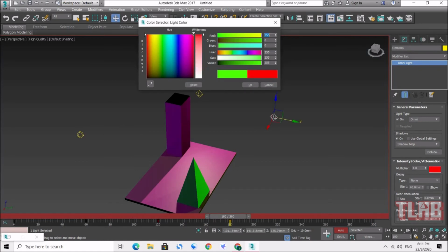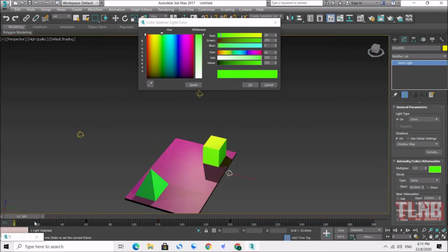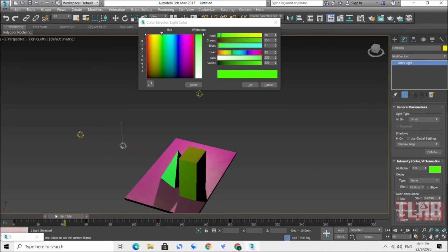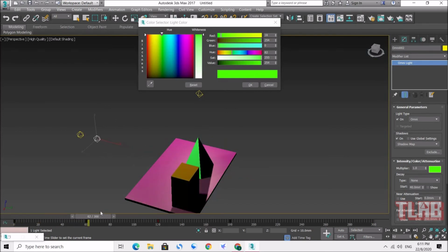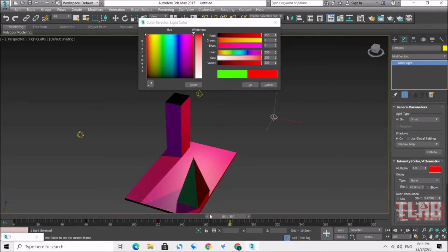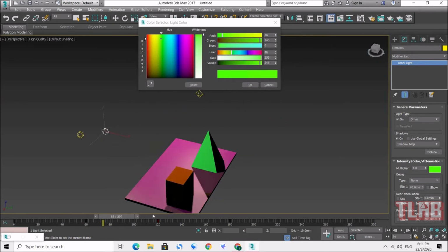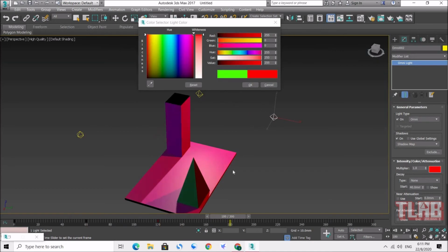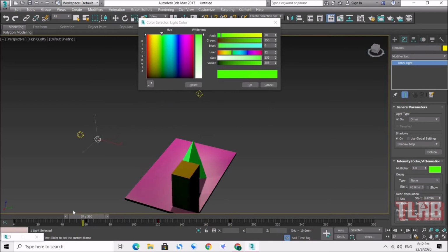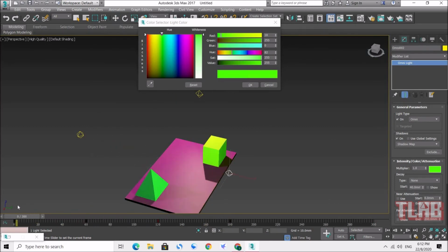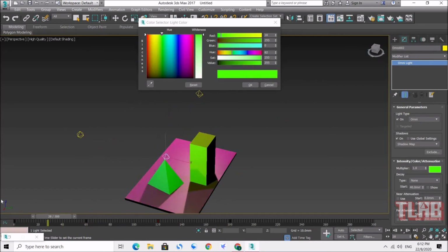You can put maybe a red color, like I said just now, 255, 0, 0. So now auto key off. Now you can see 0 until 60 is still the same color. Then from frame 60 until frame 180, you can see the number keep changing, so that means the color also keeps changing. You see this one. The 0 until 60 is the same setting, the same color. So remember this one.